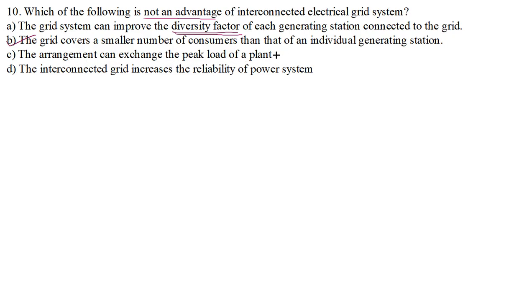That is absolutely correct. It is a big advantage of an interconnected system. We can exchange the peak load. Therefore, we require a smaller reserve capacity for each generator because of the load sharing. Option D, the interconnected grid increases the reliability.